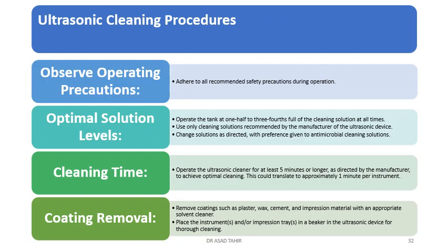Ultrasonic cleaning procedures: observe operating precautions. Adhere to all recommended safety precautions during operation. Optimal solution levels. Operate the tank at 1/2 to 3/4 full of the cleaning solution at all times. Use only cleaning solutions recommended by the manufacturer of the ultrasonic device. Change solutions as directed, with preference given to antimicrobial cleaning solutions.